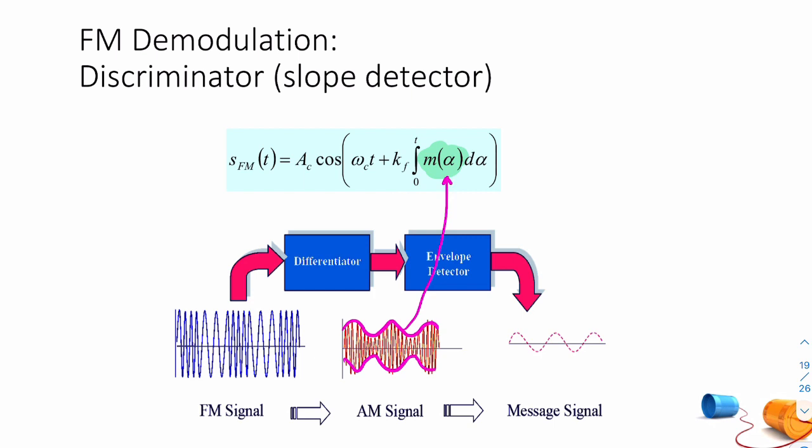So notice that here we have a frequency that changes with time. This frequency continues to change with time. So here the frequency is high, low, high, low, high. Same here, your frequency is varying. But now we've managed somehow to pull this out. We can use a normal envelope detector to then recover the original message.